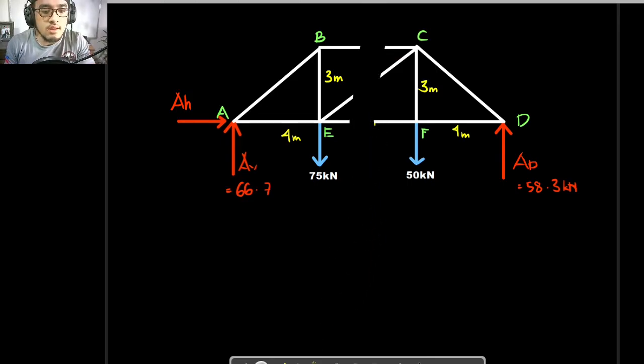But take note, guys, that if you pass a cutting plane onto the truss, the members that are cut are converted into forces. So this would be force BC, this would be force EC, and this would be force EF. Unlike in the method of joints, instead of analyzing per joint, you would be analyzing per section. Since we have already divided our truss into two sections, you now choose which section you would be solving, may it be this section or this section.